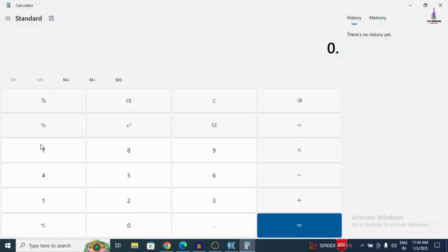So just I am taking 0.23 is the external wall loading condition system. We have to multiply this respected load with the height of the structure 3 meter and we have to multiply this respected load with the 20 so that it will get the values. 13.8 kilonewton per meter is the external wall load. In the same process 0.125 is the thickness of the wall, and if I multiply this with 3 then it will get the value of 7.5 is the internal wall loading condition system.